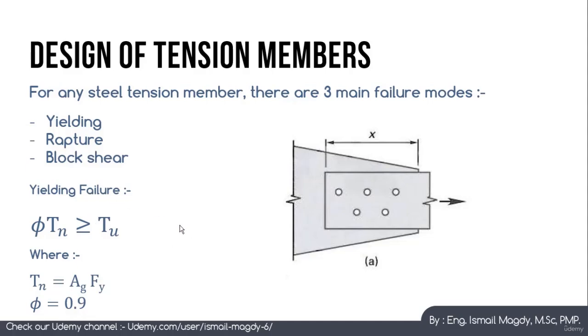For the yielding failure, this is very simple. We are governed only by the tensile force, so this is the governing equation for us, which is phi Tn has to be higher than or equal to T ultimate, where Tn, which is the nominal tensile strength of the beam, could be calculated by this equation, which is area gross multiplied by F yield, where phi equals 0.9 for the steel tension member. Here we are using F yield directly because this is a tension member and we don't have to worry about any buckling or lateral torsional buckling or any of those which we have learned in the design of beams and design of columns.